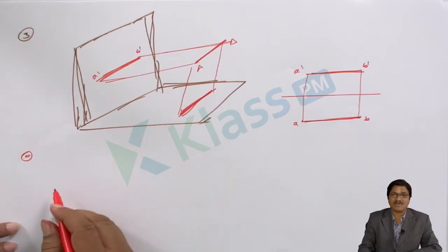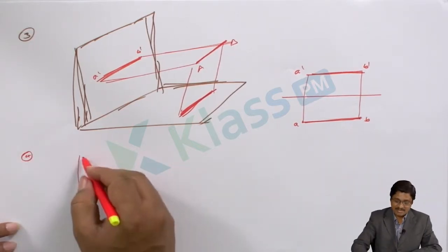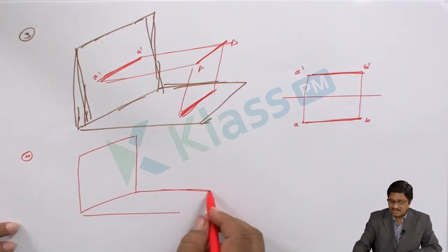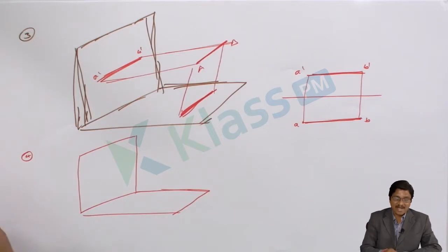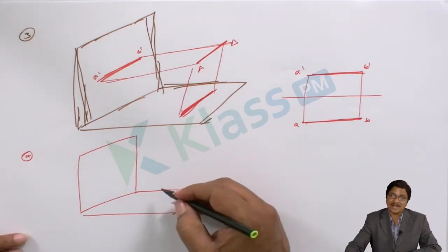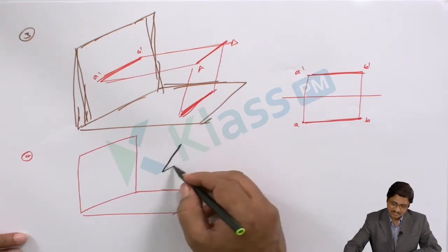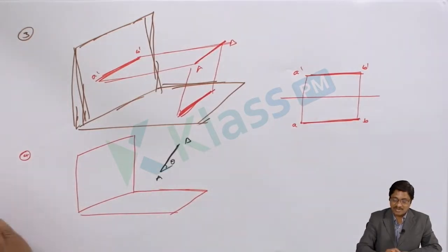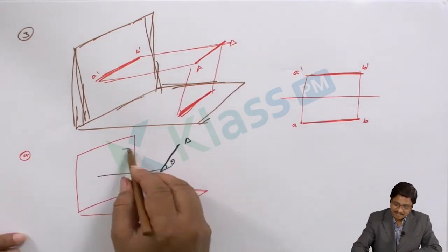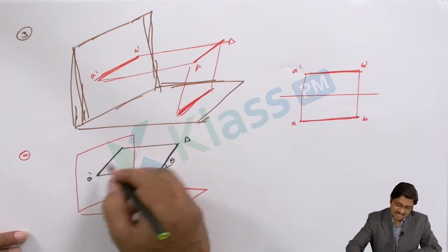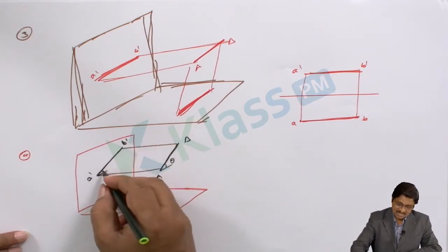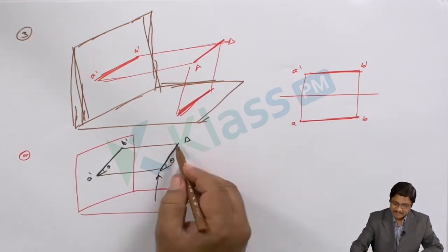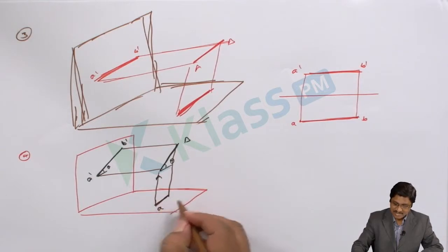In the fourth one, what does the fourth one have? It is line projection representation with a vertical plane and horizontal plane. So now this one changed. What changed? It is parallel to VP but inclined with HP, in this orientation. Let theta be the angle it is making. Now this is point A and this is point B. Once you get the front view, this is A dash and B dash. This is theta. Whatever the top view, in the same line, here is A, here is B.